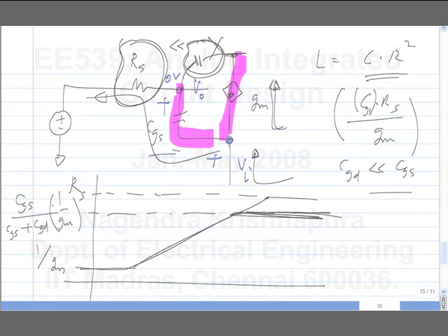Now again, see, if you try to use Miller's theorem, this side it has only passive components. So the voltage V0, if you think of it as an amplifier from this Vi to this V0 and connect a capacitor across it, this transfer function depends quite a lot on CGS. So you can't remove it, evaluate the gain and put it back and see.